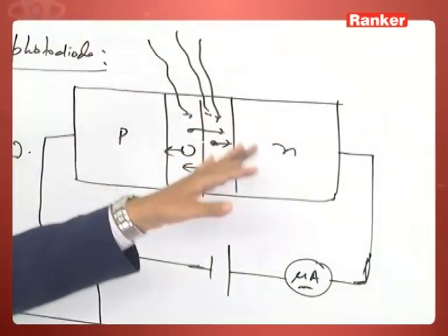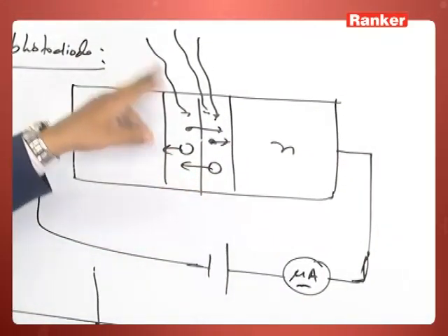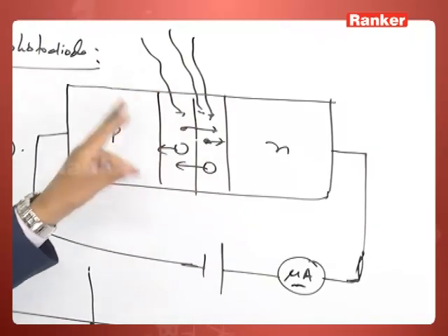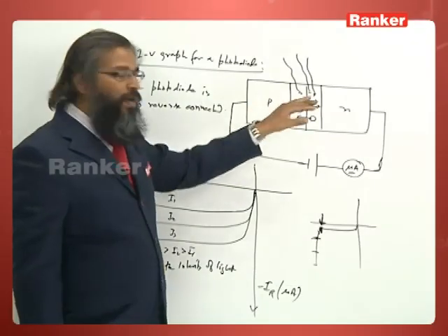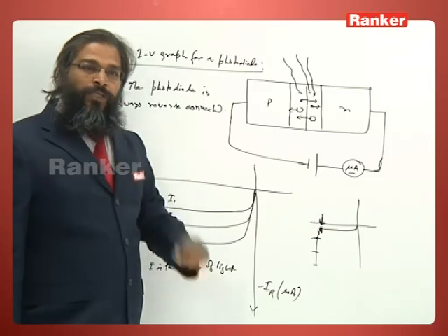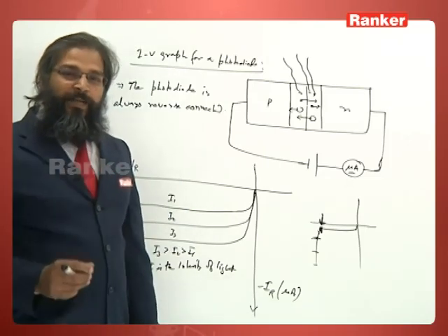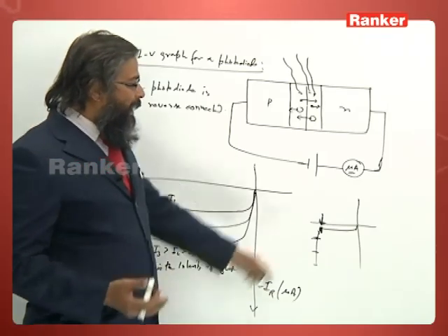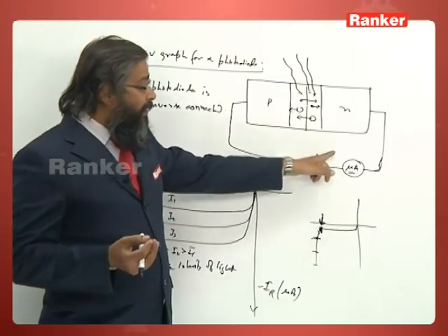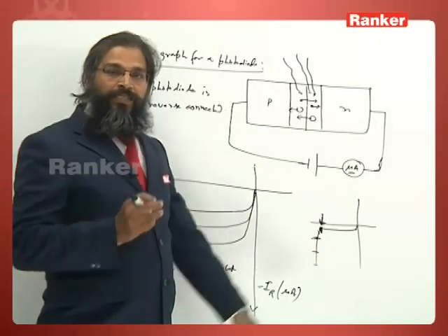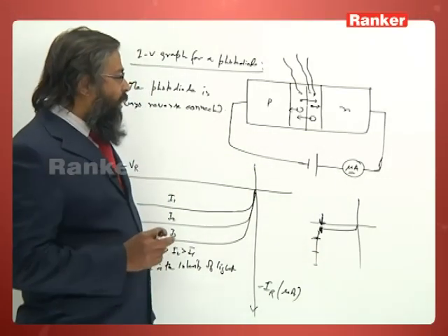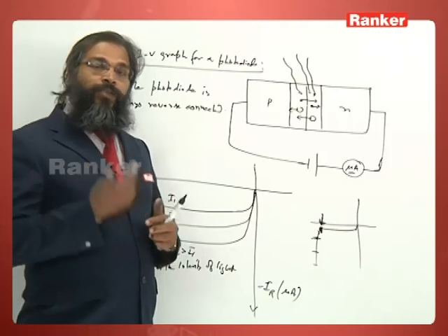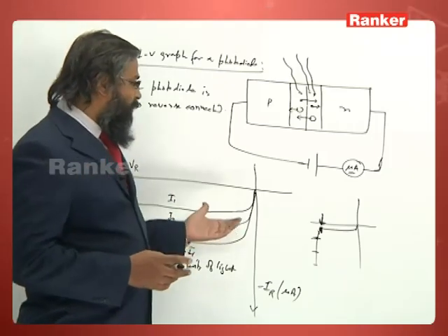But if it is forward bias, again the same thing will happen at the junction, but the order of current is in milliamperes. So, suppose a small increment takes place for a milliampere current, that won't be noticed, but a small change in microampere currents can be easily noticed. That is why the change is easily noticed in a reverse bias.